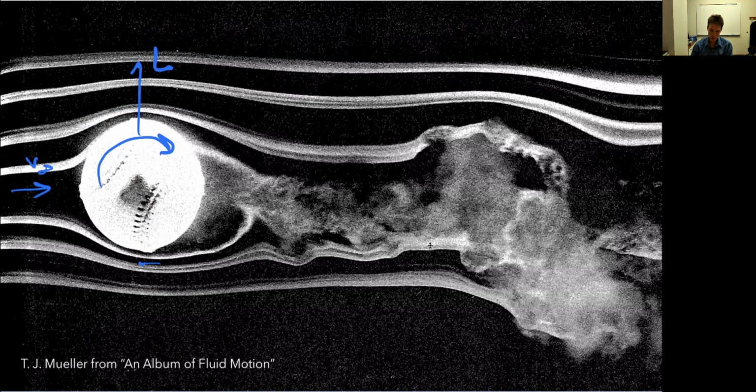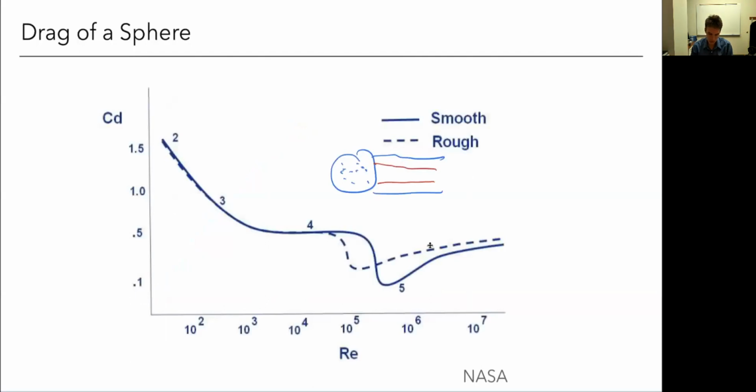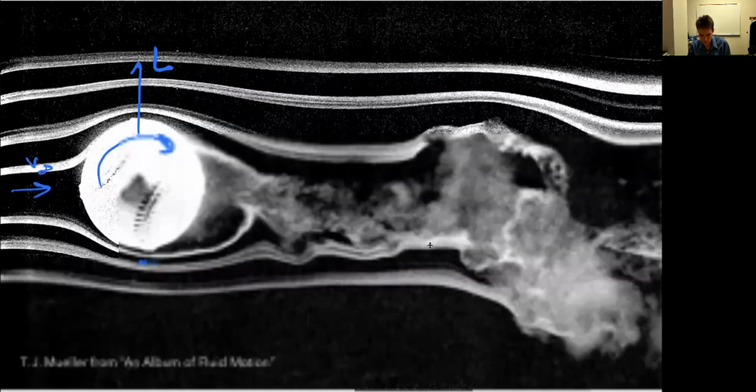This is a little more subtle, but based on our discussion, we might think that this has to do with boundary layers, and indeed it does. The idea here is that if we look at this picture we've discussed already, from laminar to turbulent, we get this change in the boundary layer behavior. But if you notice in the turbulent case, as I increase in Reynolds number further, the drag actually goes up. So if I call this my solid, and here's going to be a dashed line over here, just to represent a high Reynolds number, this wake actually starts getting bigger again as I get to even higher turbulent speeds. So with that in mind, this last picture will explain this.